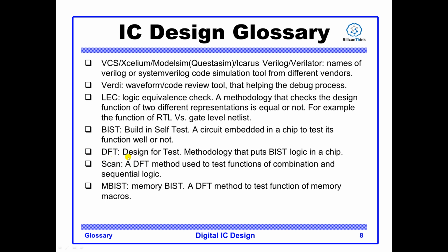DFT stands for design for test. This is a methodology that puts BIST logic in a chip. Scan is a DFT method to test the function of combinational and sequential logic. MBIST, memory built-in self-test, is also a DFT method to test the function of memory macros.